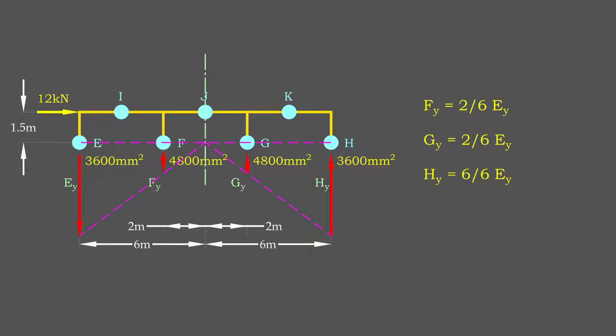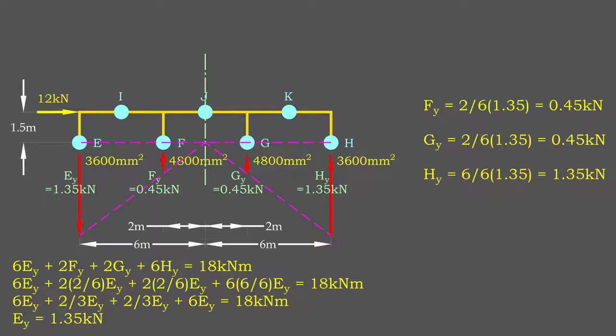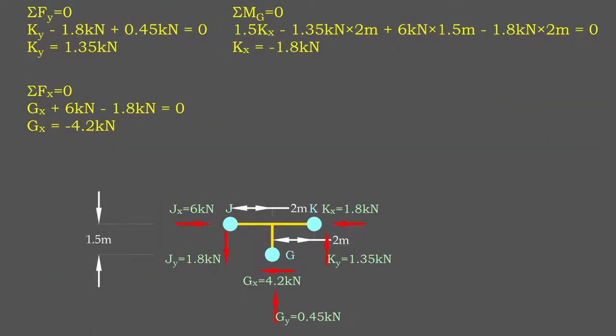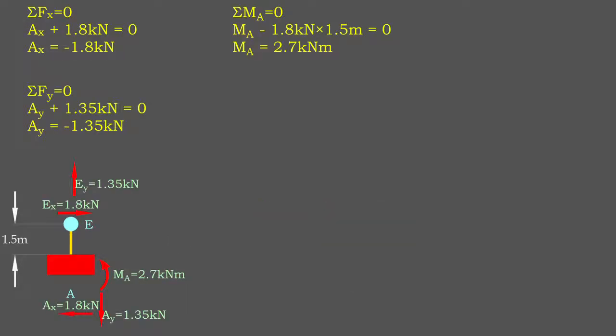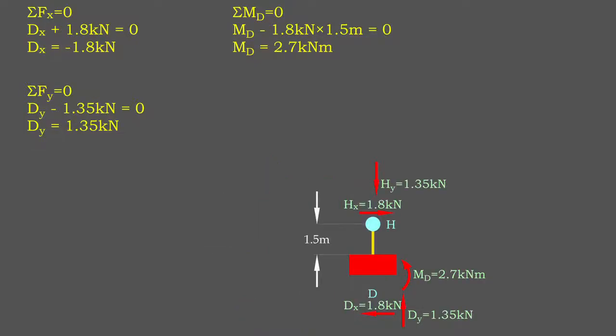Therefore, by using similar triangle correlation, we can simplify the equilibrium equation and make it consist of only one unknown. After solving the unknown, we can use it to determine axial force in remaining columns. Up next, the procedure is similar to the portal method. The frame is dismantled at hinges, and the unknown forces are solved part by part using equilibrium equations.